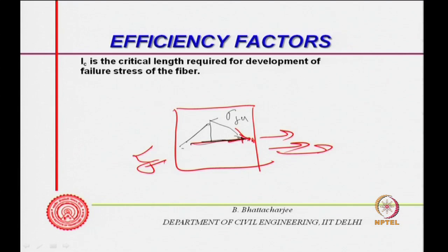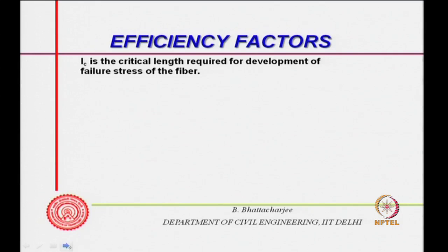So, it is a kind of development, the length required for development of the full failure stress, the ultimate stress in the fiber. That is what I am calling LC. So, this diagram will show you, this is my LC, and this stress will be sigma fu.